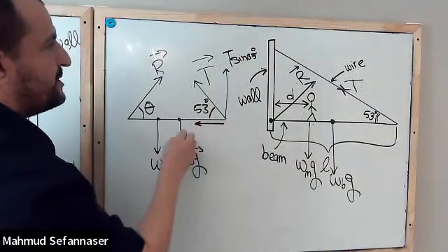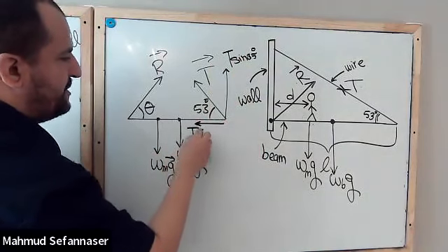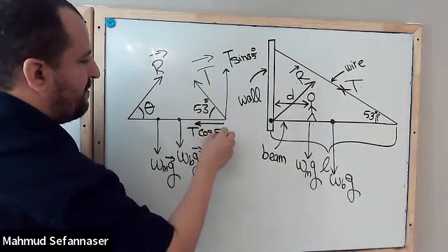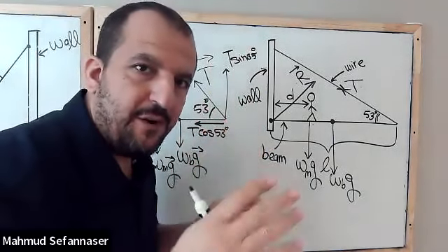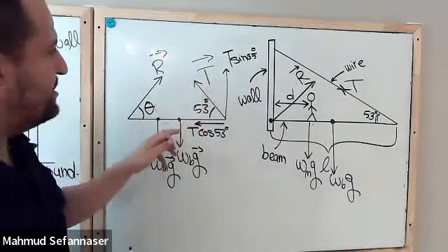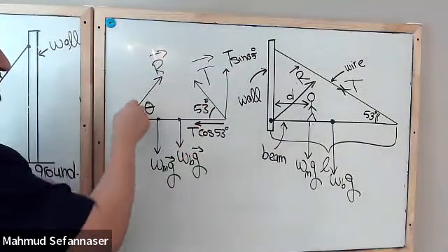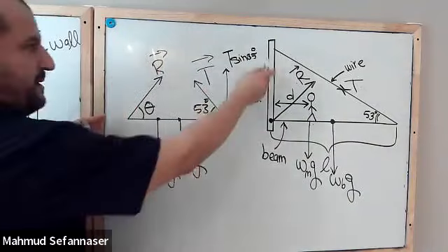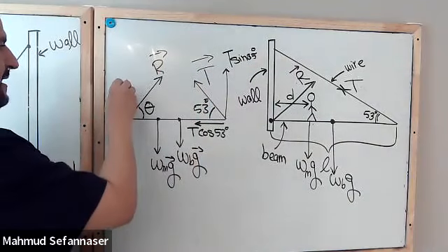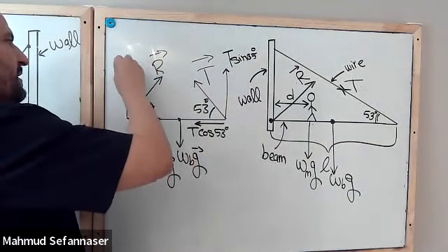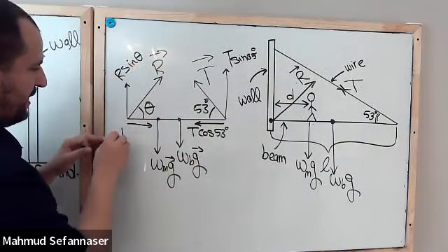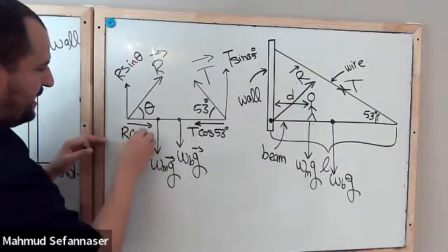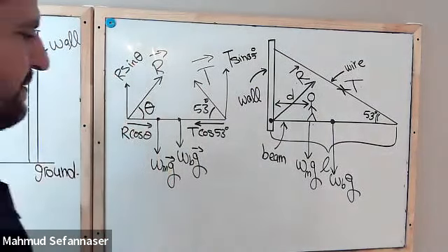And in this direction, I will have T as a magnitude and cosine 35 degrees. That's very nice, guys. We decomposed the first force. Now I will come to the force that was exerted by the wall. So what I will have here is R sine theta in this direction, and here I will have R cosine theta. This is very nice.